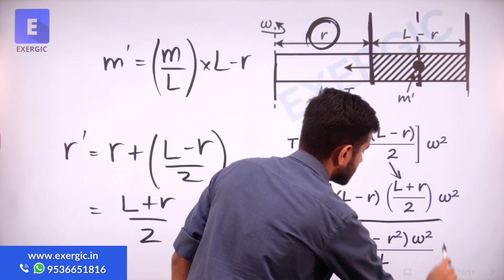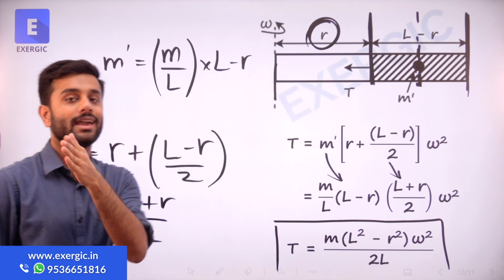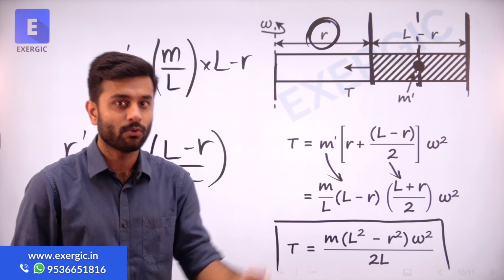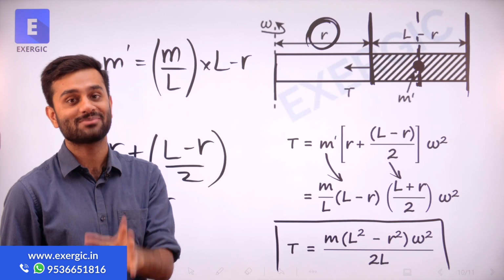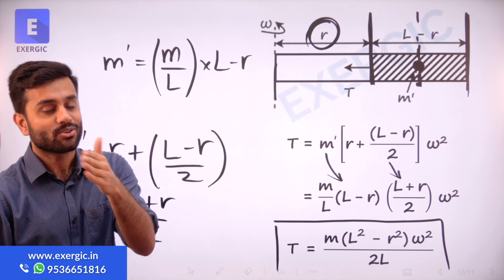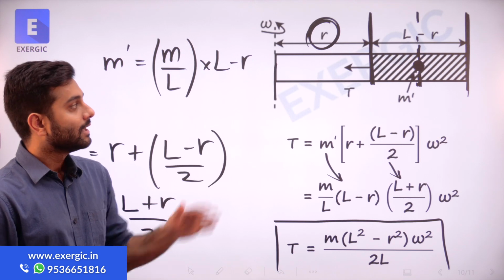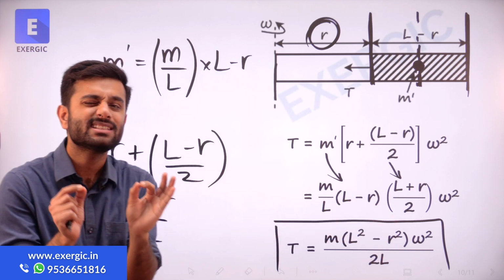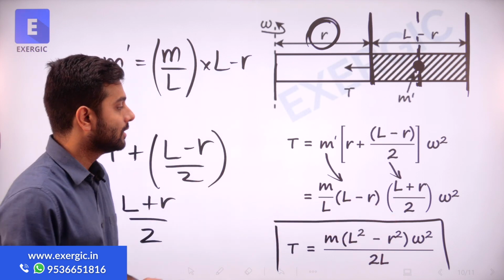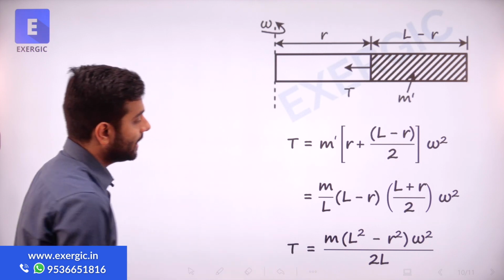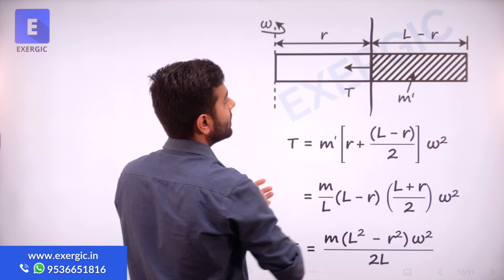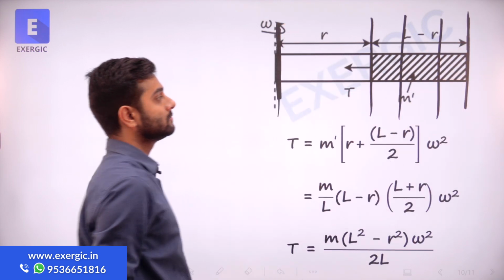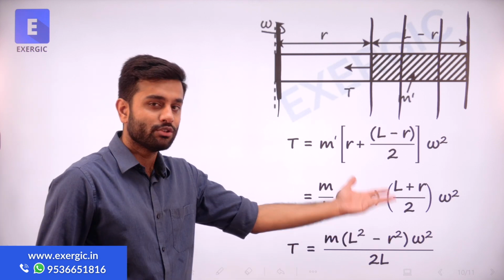This is the expression which denotes how the axial tension, axial force, centrifugal force, longitudinal force, radial force, all of the names representing the same tension, is going to vary along the length, along the radius, you can say. Please note, small r is any general radius, any general section. This section can be here, here, here, or here. Just put the value of r and you will be able to get it.